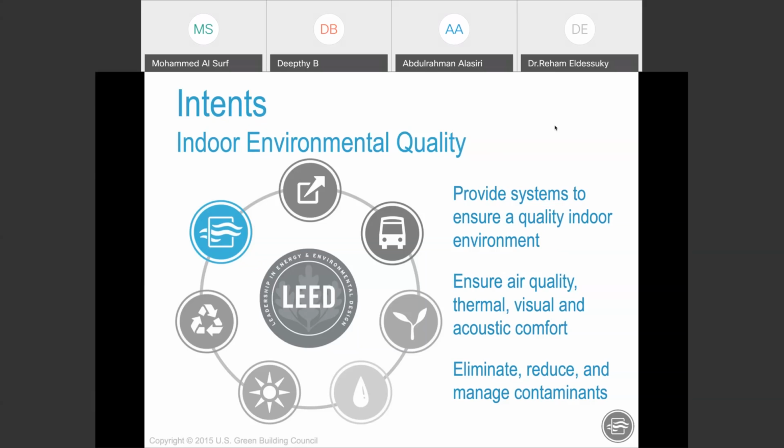So this really connects back to the materials section before, where the choice of the material that we select will have a big impact on the quality of the indoor environment, either through the contaminants that emit from it. So we have something we call the VOC, volatile organic compound. So that's something to really consider here, to really select the material with less environmental impact, because it will help us improve the indoor environment quality of the building.